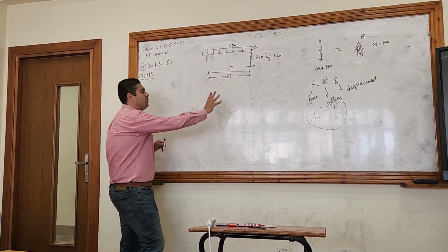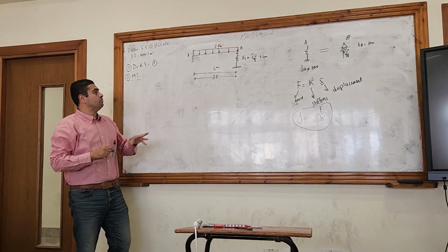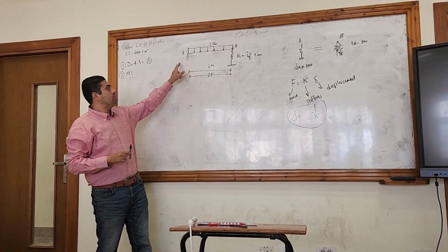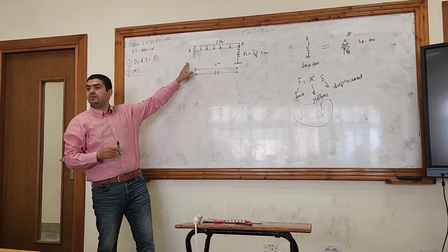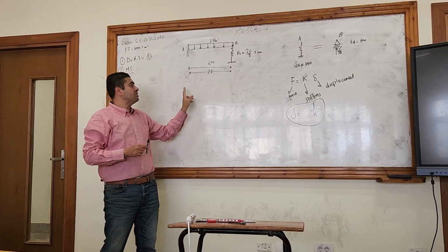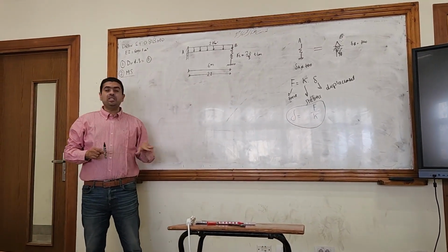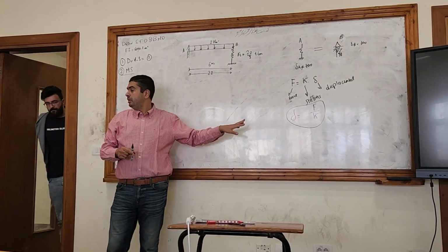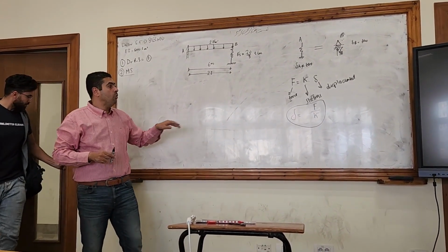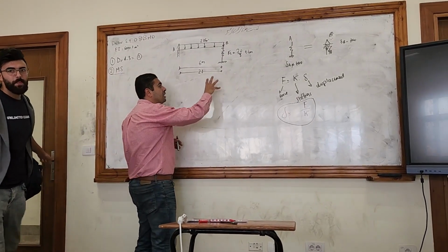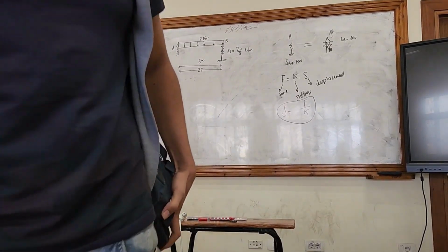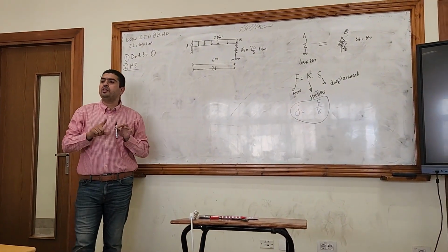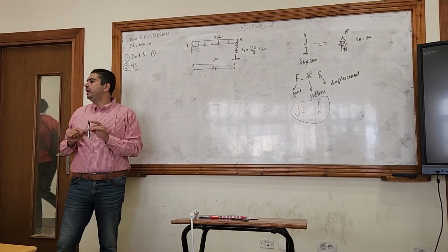Because if you left the spring and you chose the main system to be hinged-spring, so you removed the moment at the fixed support A, it will be so difficult for you in the solution. Why? Because the spring will provide a vertical displacement, so it will differ totally in the condition at the end.